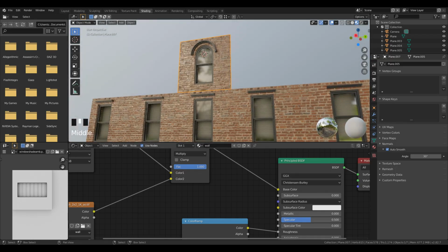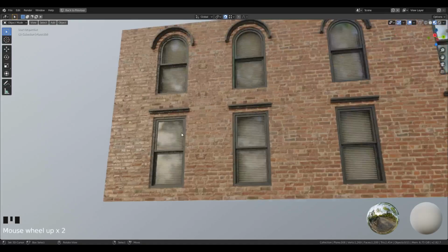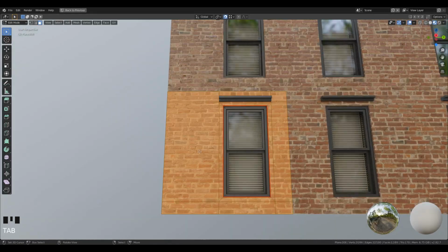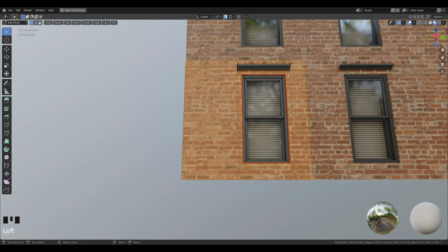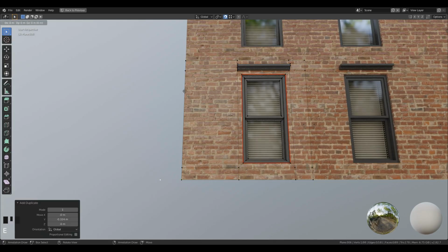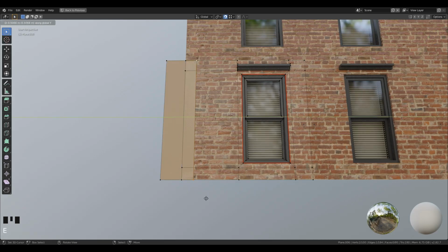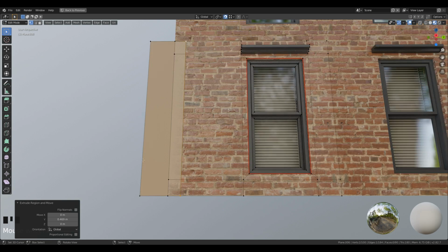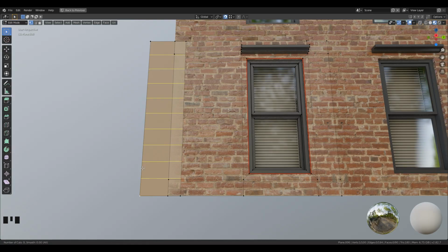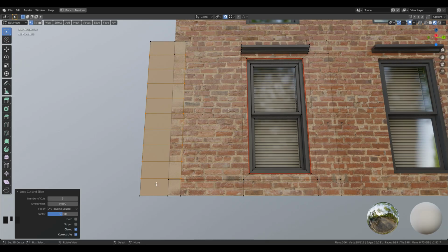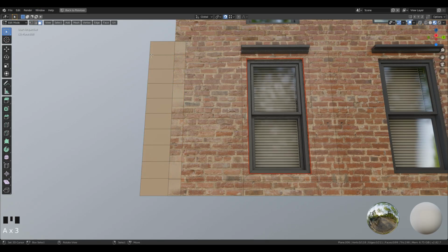After that, select any of the side panels and in edit mode duplicate the bottom left vertex and extrude it up with snapping on. Then extrude it towards the panels. Now you can add edge loops to it and try to use an odd number to get an even number of faces on the panel. Then just delete the upper faces and leave the bottom two.